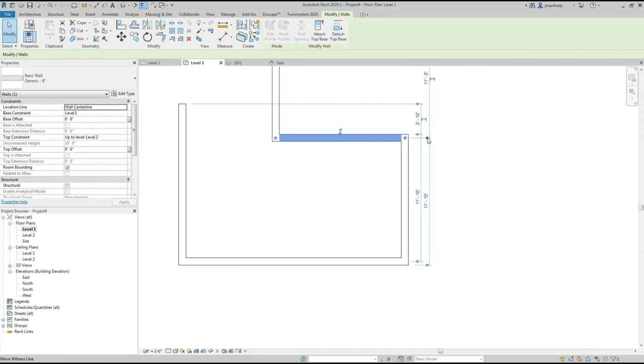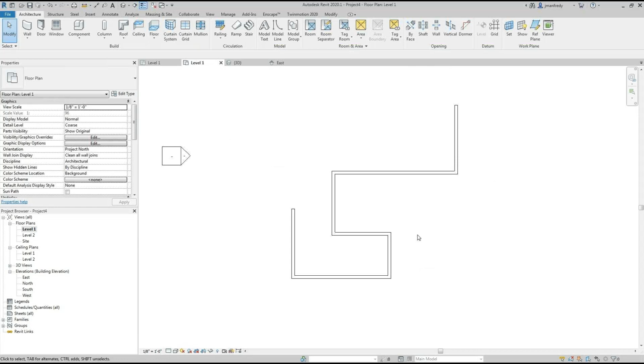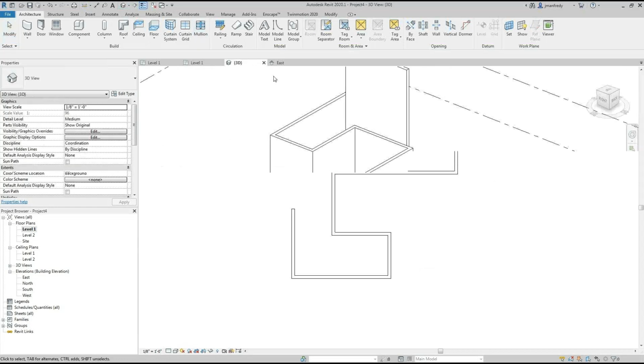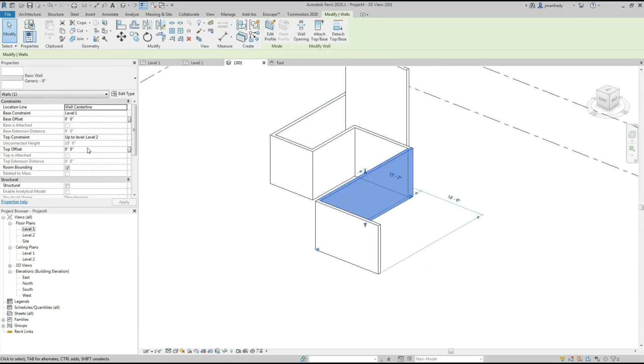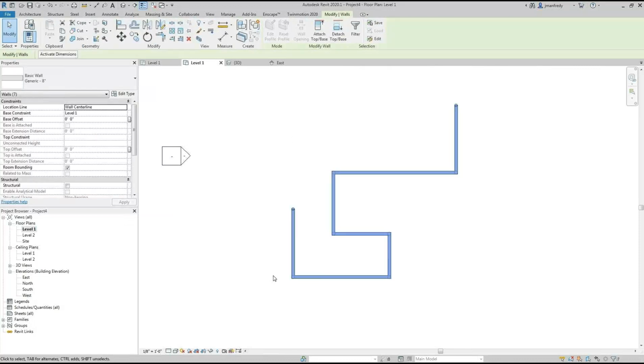Just move that around, that one there or that one there. Whichever one completes the task for you. And just type in over. And that's how you can draw things in Revit. And the important thing here is to make sure that the heights here make sense in your properties. Another thing you want to make sure you do, I'm going to drag my mouse through everything, hit delete.